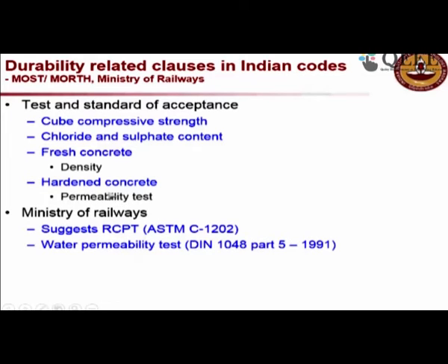We discussed so many different types of durability tests in the previous slides, but what we see here is not all of them are being implemented yet in Indian codes. So there is again a long way to go, but the codes are being modified as we talk, so that we can ensure that our future constructed facilities will last longer and the concrete will be of better quality. So RCPT is one of the most widely used test methods to check the resistance against chloride attack. But of course, as a point I would mention, there are some issues associated with RCPT. You cannot blindly go with the numbers alone.